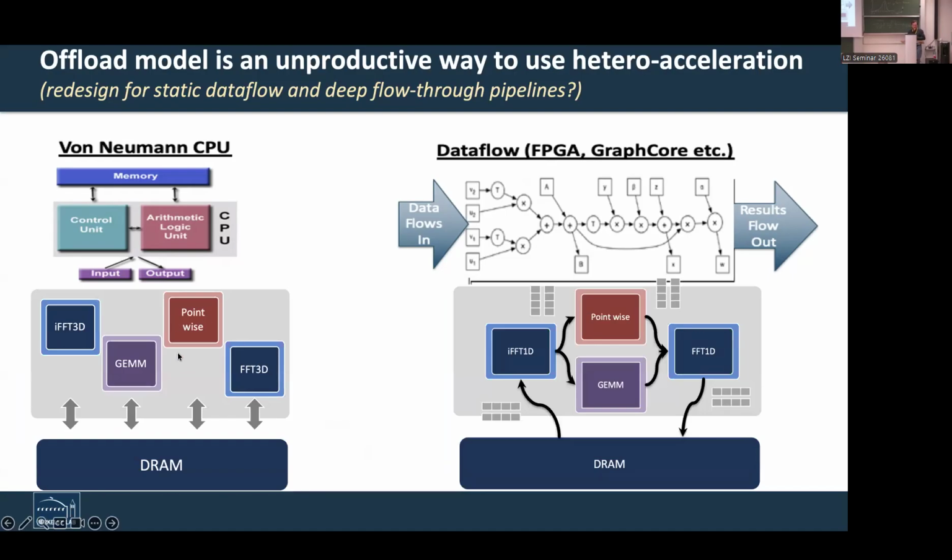So the left-hand side lends itself to having highly tuned libraries where I invoke the FFT and then I invoke the GEMM. I do this sequentially, and each time I run the data through the processor and back out again. This is encapsulation. This is how libraries work. But if I am doing it as a circuit design, I actually have to set things up so I flow blocks of information between these ALUs, and then I don't take a round trip back to memory between each of these optimized cores or function blocks.